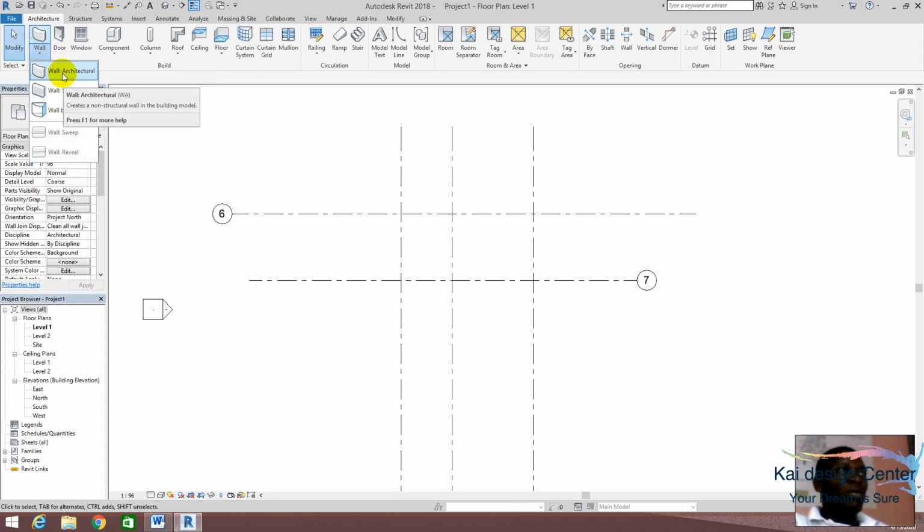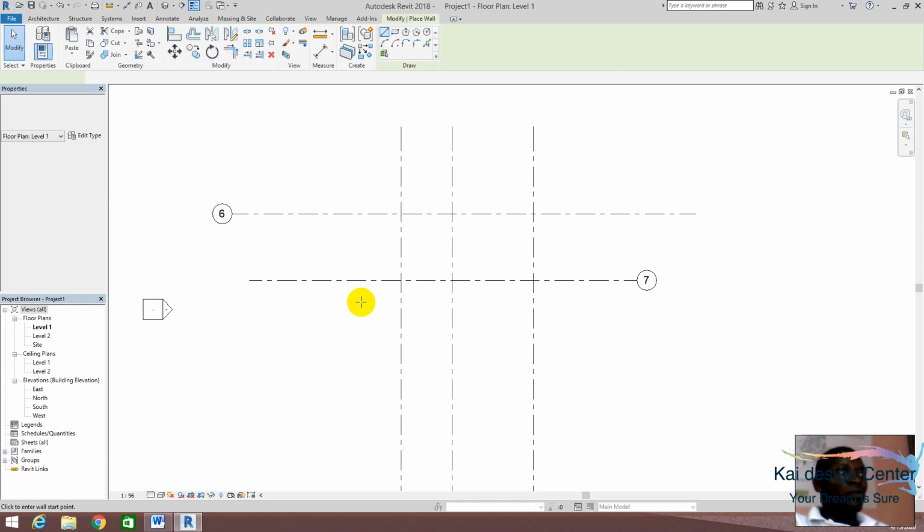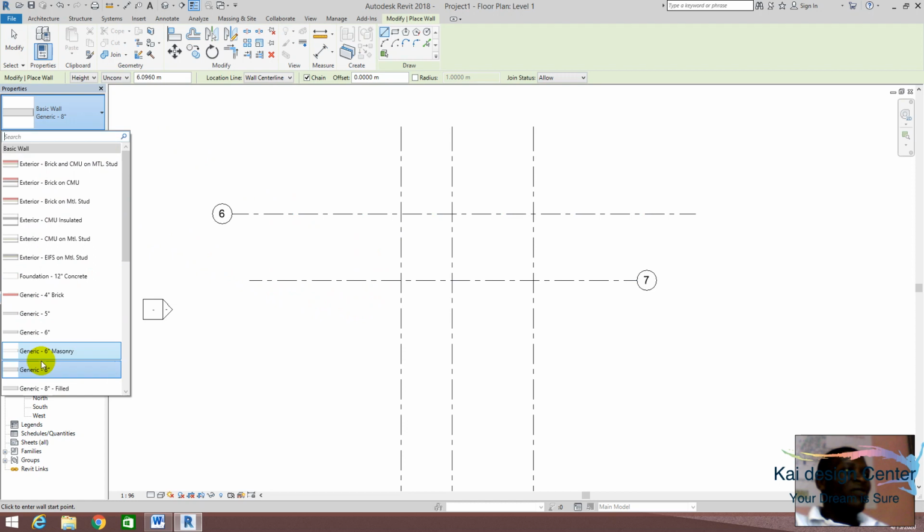So what we'll do is I will take what we call architectural walls. Under architectural walls we have so many of them here. You just need to choose one of the walls and define it your way. In a later exercise we'll see how to work with defining exteriorly, interiorly, the quality. But today we want to see just how to configure a wall. Let it be within the reach of your country. In my country, we are using a wall of 15 for elevated walls and a wall of 20 for foundation. So we may be in different environments, so we have to configure it.